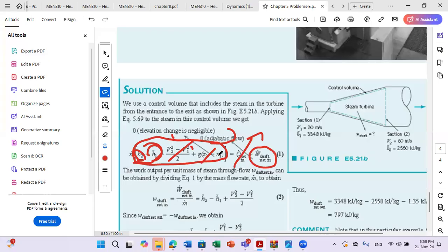So when you replace in this equation, you can get W dot over m dot, which is the value of power per mass flow rate that can be extracted through your turbine. And here we can see that when we go through the turbine, the enthalpy will decrease a lot because the turbine will extract energy from the fluid. It will extract energy in pressure